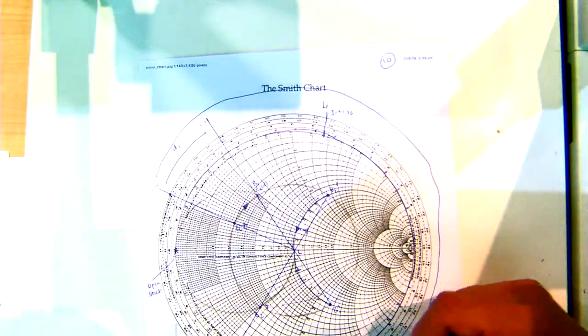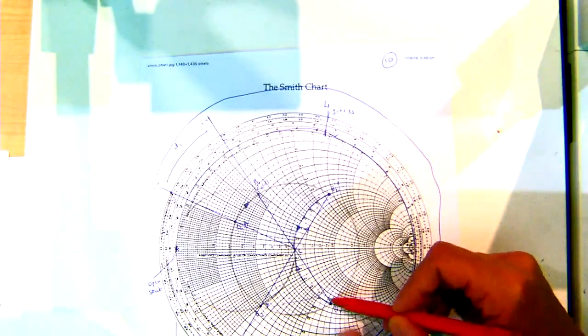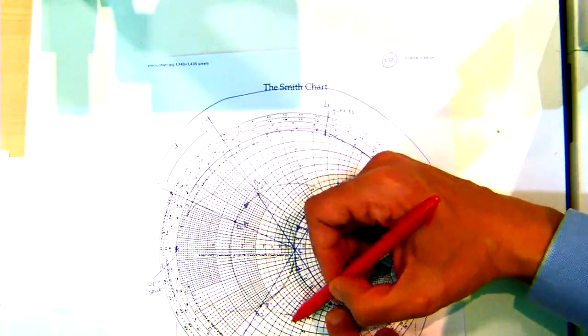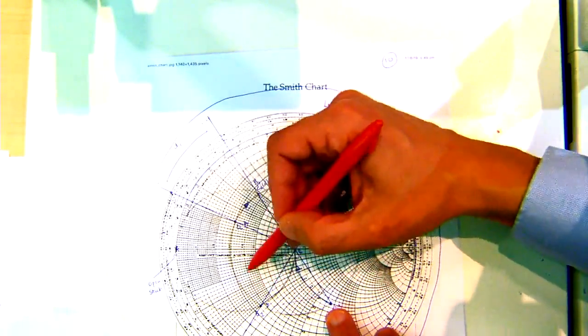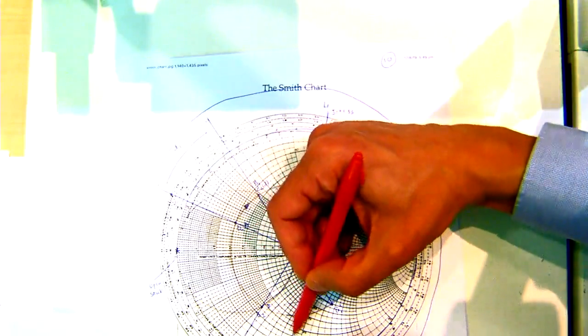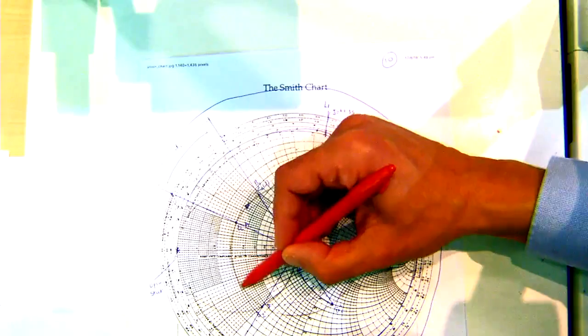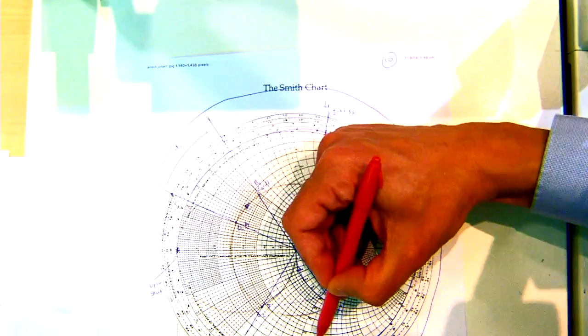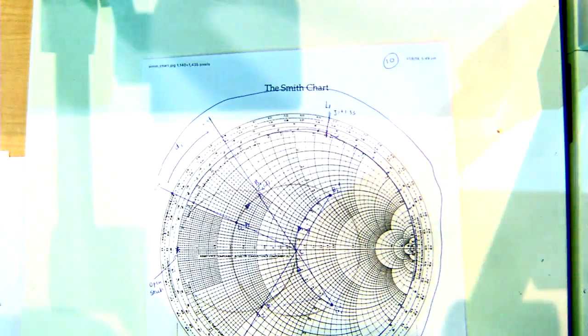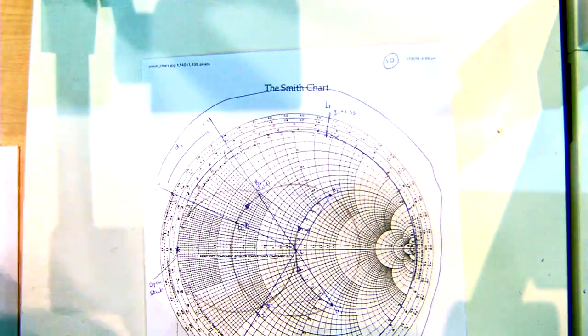Okay, so you find the imaginary bit here, minus 1.2. It's about 6 o'clock. All right, so 0.3, we said the 0.3 line is here, because we're looking at 0.3, and then we have to find negative 0.12, it would have been there. It's got nothing to do with the question, I'm just trying to make sure that you can actually find all these locations on the Smith chart. Fantastic. Okay, so the next thing we need to do is what?